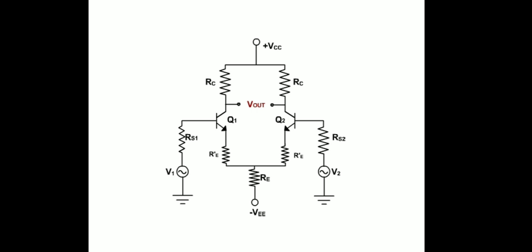Well, this is the basic circuit representing the differential amplifier. We are having two BJTs Q1, Q2, their emitters being coupled, and the signals are being applied at the base of the Q1 and Q2. The important thing is the Q1, Q2 are matched transistors so that the output is not affected by the devices, and thus the output is the difference of the signal being applied at the base of the two transistors Q1 and Q2.